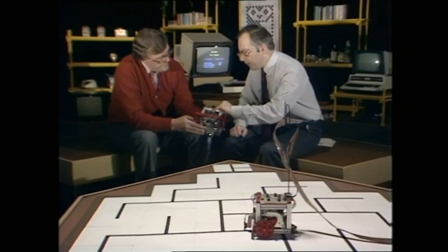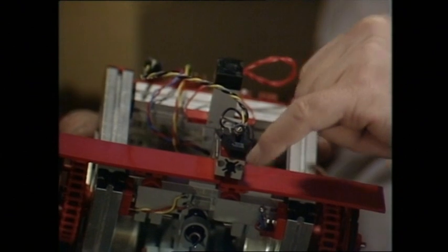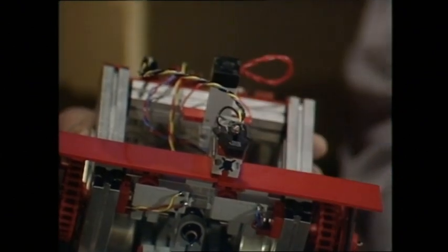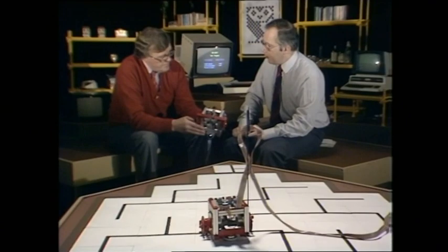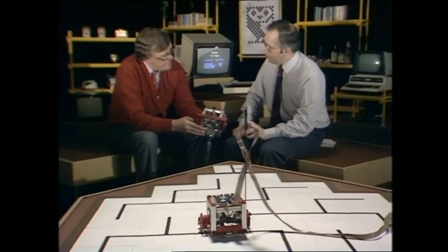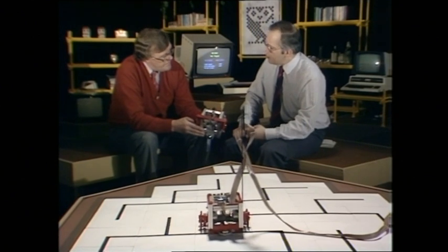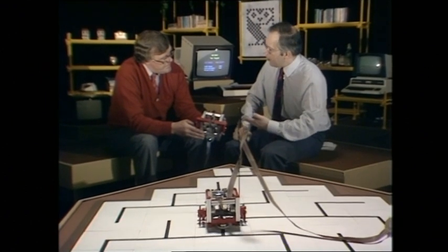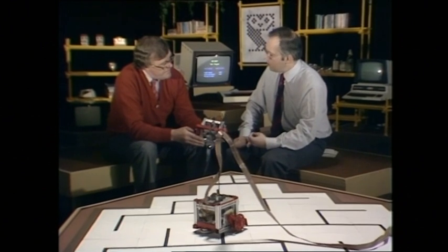This one's really rather different. This sensor emits infrared light on this side, which is reflected off a surface, and then the infrared is picked up here. So it can follow either a white line or a black line and determine which it's on. It's actually an analog device, but the computer senses whether it is above a 50% level, whether it's above grey. If it's brighter than grey, it says that must be white. If it's darker, it must be black.